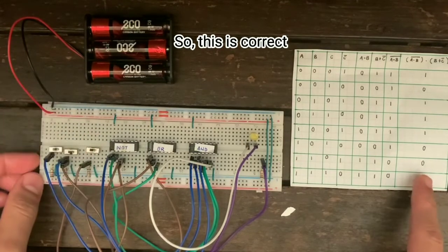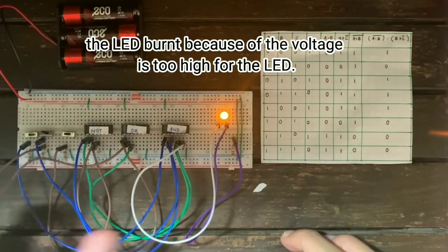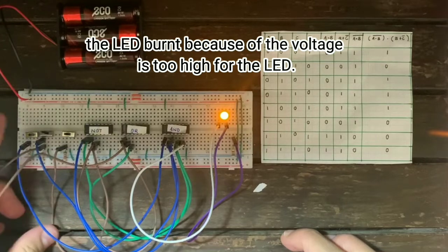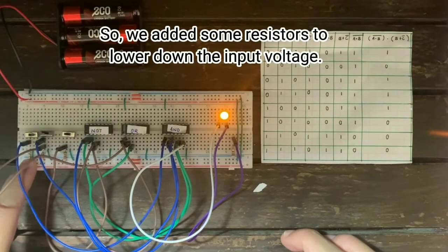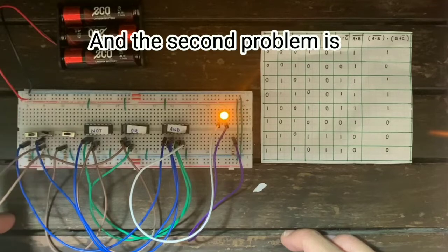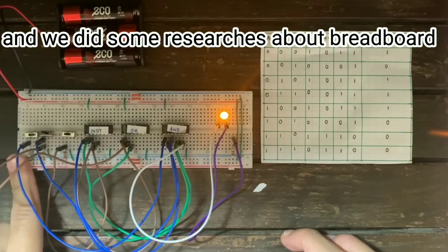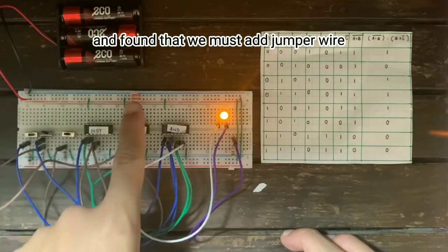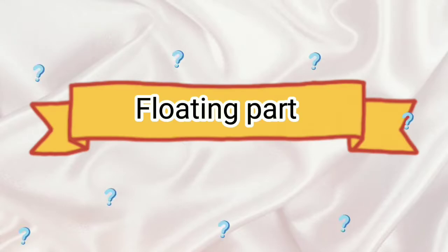So this is correct. So the problem that we face during this project is the LED burn because the voltage is too high for the LED. So we add some resistor to lower down the input voltage. And the second problem is the connection on the breadboard is not correct. And we did some research about the breadboard and found that we must add a jumper wire to connect this part of the breadboard to this part.